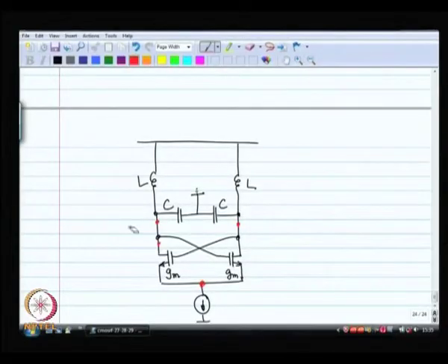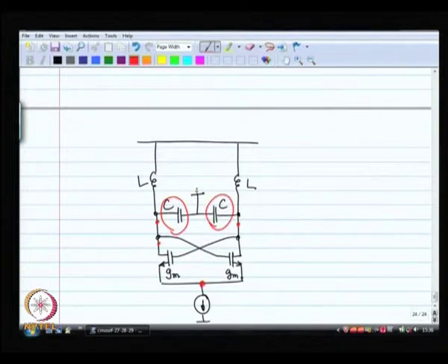There is C drain to body capacitance, which once again looks exactly like the load C. So, drain to body also looks exactly like the load capacitance, and as a result I should not be bothering about it. So, all of these parasitic capacitors are really not of much consequence. All of them can be lumped inside these two capacitors, all right.